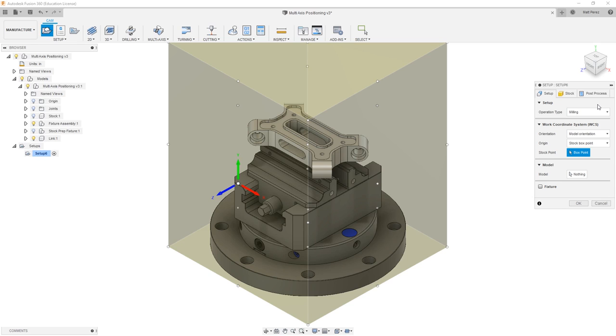And also note that we currently have our preview functionality for machine definition turned off. If we have that turned on, you'll see an extra section in here where we'll need to select an applicable machine. Using the machine definition will allow you to define parameters inside of the machine and have an extra level of checks in place. What we want to do in this lesson and these sets of lessons is understand multi-axis positioning. So we're going to be focusing on the basics here in terms of how we're going to set up our new milling operations and how we're going to position and use the tools.